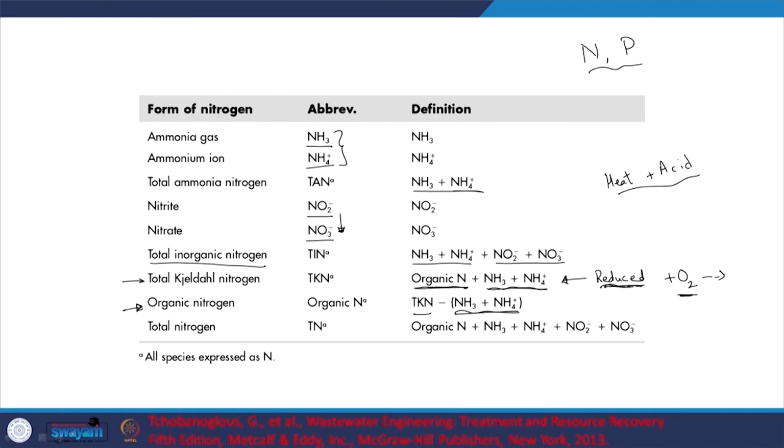I can see to it that the pH is changed. We know the pH pK relationship, and I can see to it that this ammonia changes phase from the aqueous phase to the gaseous phase, and typically that is done during boiling. So, first I am going to boil it and see to it that the conditions are such that ammonia leaves the aqueous phase and goes into the gaseous phase.